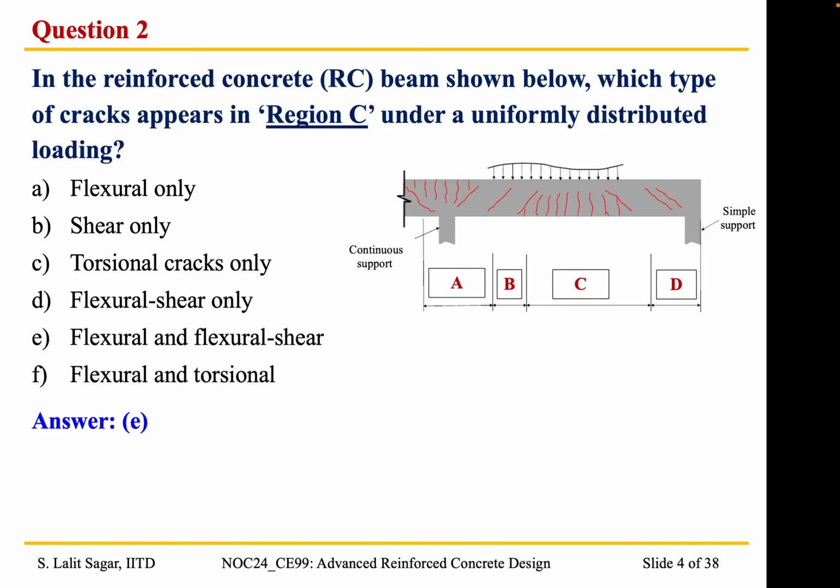And if we see the region C, since it is covering a larger part of the span, it consists of flexural cracks, as we can see here, which are perpendicular to the longitudinal axis, and we also have these flexural shear cracks, that is, they are initiated in the beginning either as a flexural crack or a shear crack, and then they also become flexural shear cracks. For example, if you consider this particular crack, because of the high shear force, we can say that